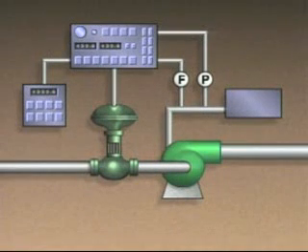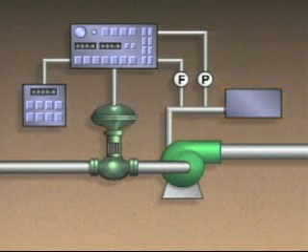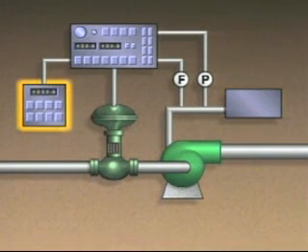For example, here's a simplified illustration of a safety interlock system that's associated with a pump. A lube oil system provides the pump with lubricating oil. A process controller automatically controls the operation of the pump by starting and stopping the pump's motor as needed. An operator can also use the process controller to start and stop the motor manually.